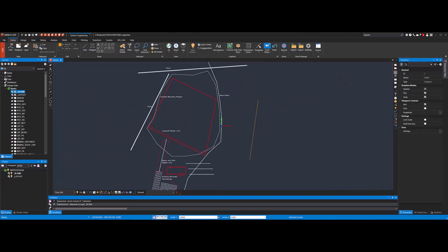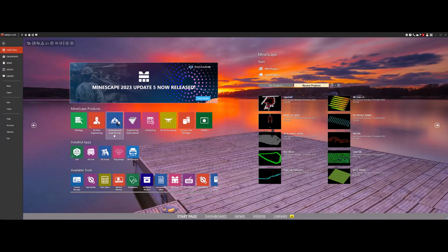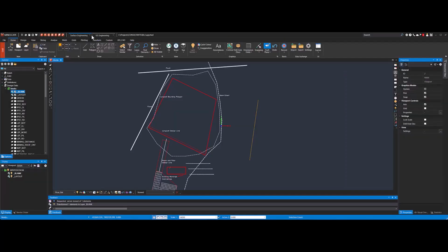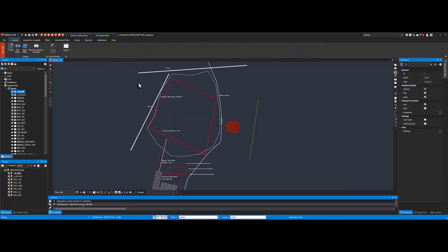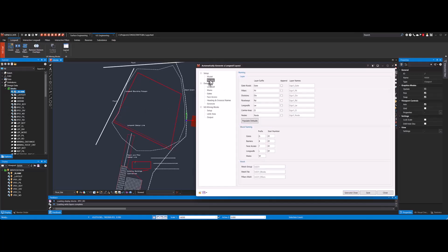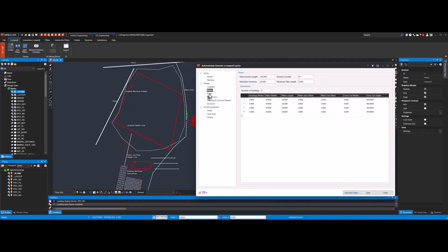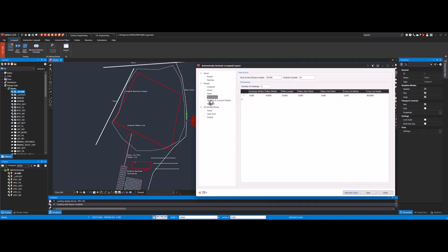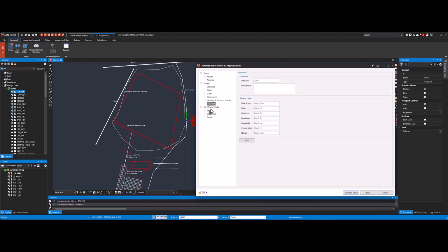Next, let's shift focus underground. MineScape provides tools purpose-built for underground coal operations. On the screen, you'll see a boundary layer displayed that defines the underground mining limit. This boundary was generated by referencing the stratigraphic model, analyzing seam thickness, splits, and geological structure, all critical factors for designing underground layouts. Using RapidCAD to lay out a center line, you can generate panels.